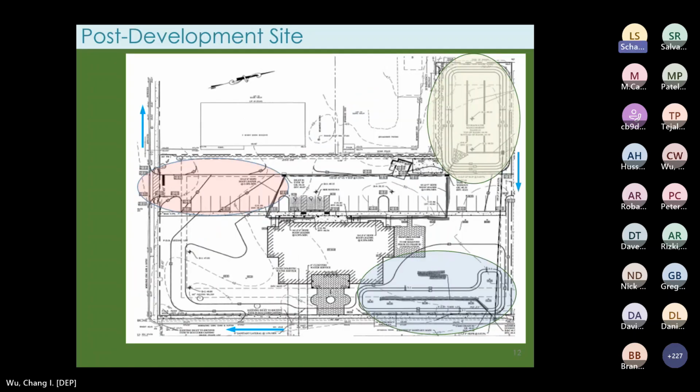All right, the proposed development consists of a 3-story apartment building in the center with a parking area and associated site improvements totaling about 1.4 acres altogether. The roof generated runoff would be treated by a bioretention system with an underdrain to provide stormwater runoff quantity control. And that basin is in the blue oval at the eastern corner of the property, and it then discharges easterly to the MS4 system along the bottom of the slide.